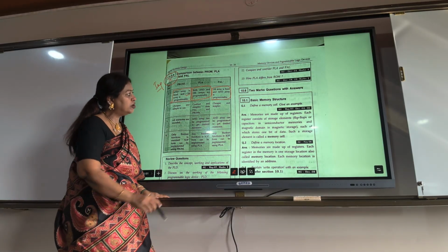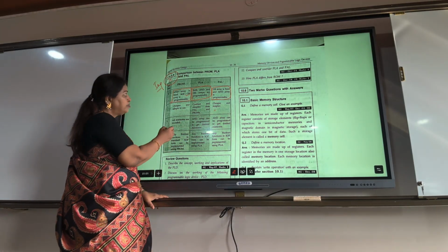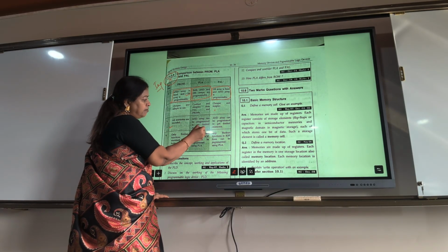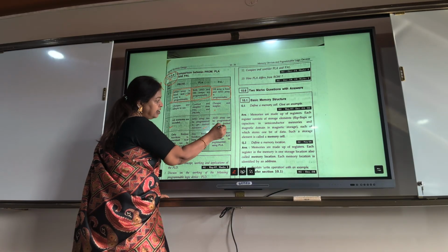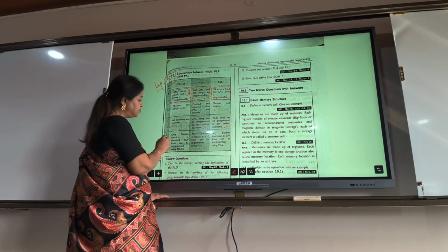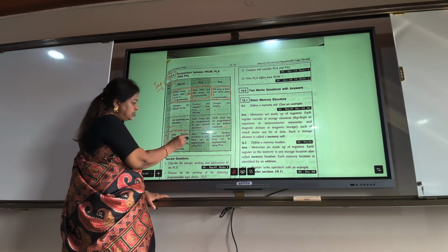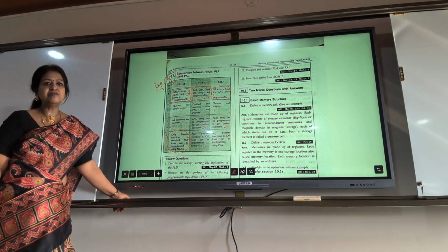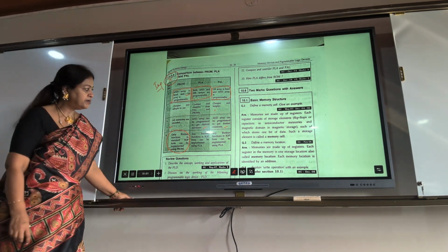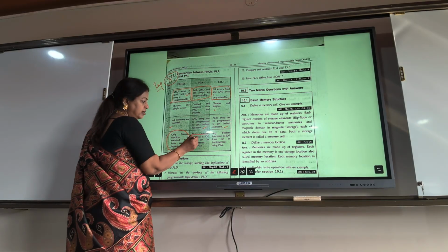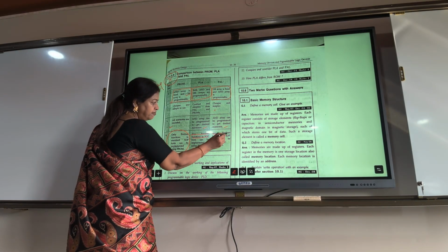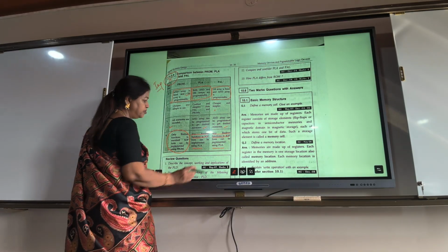In PROM, all minterms are decoded. In PAL and PLA, the AND array can be programmed to get the desired minterms. In PROM, only Boolean functions in standard SOP form can be implemented. Any Boolean function in sum of products form can be implemented using PLA.